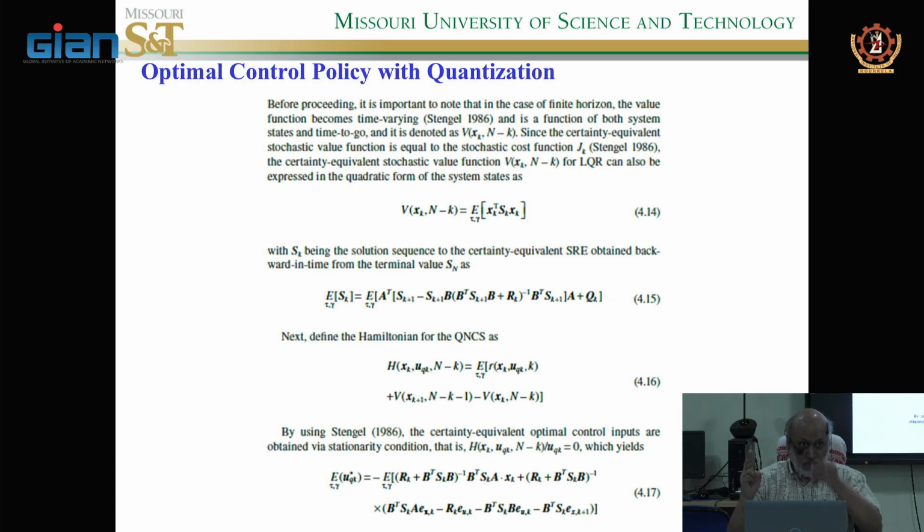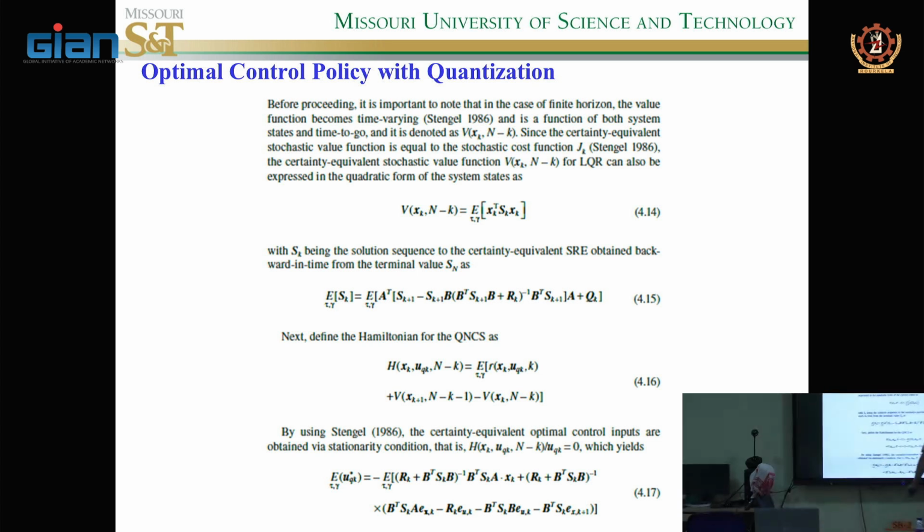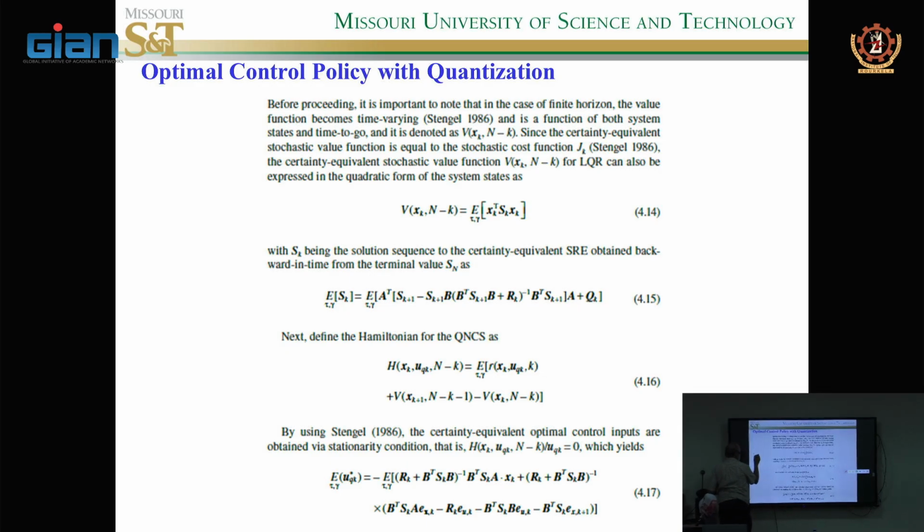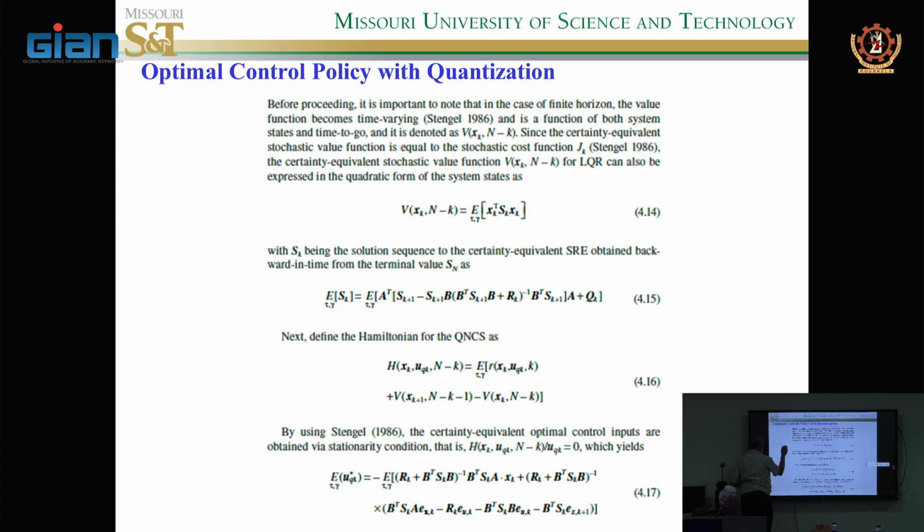You see? So the derivation is identical to what we showed before, but now what you do is wherever there is x of k, you write it as the quantization error plus that quantized value. So in other words, remember, what I'm doing is I'm defining, which doesn't show here, the quantization error, let's say E x comma k is equal to x of k minus x of qk.